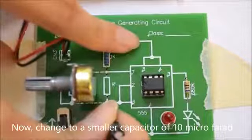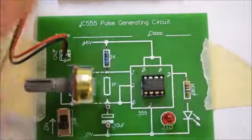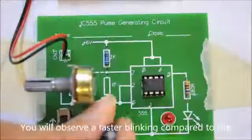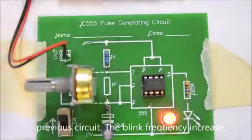Now, change to a smaller capacitor of 10 microfarad. You will observe a faster blinking compared to the previous circuit. The blinking frequency increased.